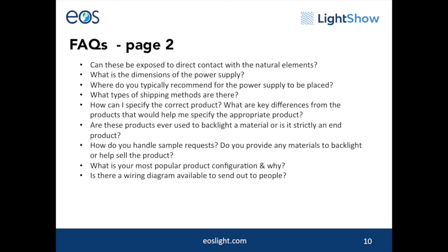What are the dimensions of the power supply? A few options are available, such as a rack mount driver, which fits into standard 19-inch wide networking racks, and surface mount drivers intended for outdoor applications. The surface mount drivers are also applicable for indoor applications where networking racks are not feasible or practical. Where do you typically recommend for the power supply to be placed? Power supplies must be within 100 feet of LightShow panels and within 200 feet of LightShow Max panels. Surface mount power supplies are available for projects where indoor power supplies are not practical or feasible, either because of exposure to the elements or dimensional constraints.